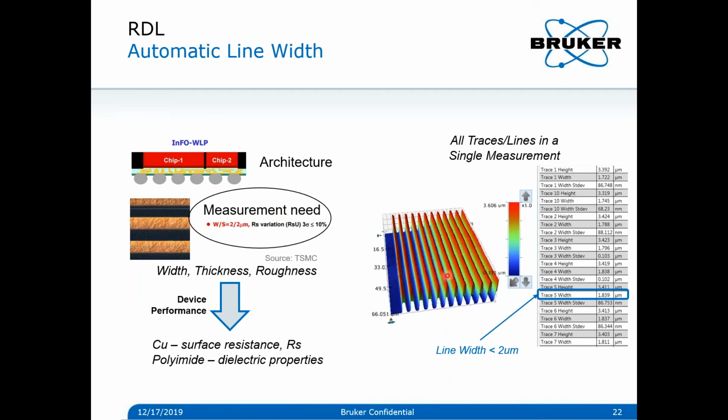In that case, we have developed a dedicated analysis where, whatever the measurement we take with a series of lines like this, the system will find the main orientation, the skew, the theta angle to align them well, and then be able to measure each individual RDL finger, measure the width fluctuation along this line, and get an average with average depth as well as average fluctuations.